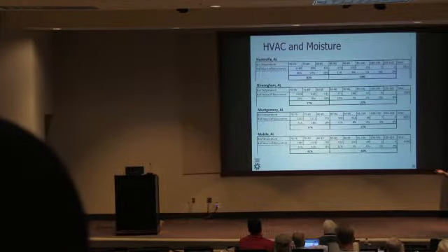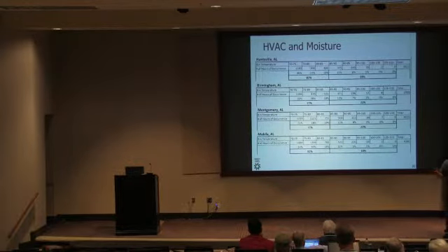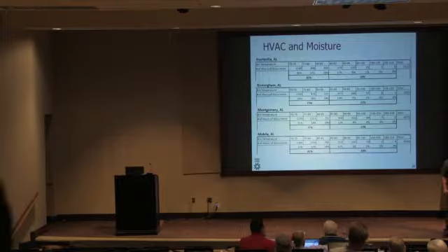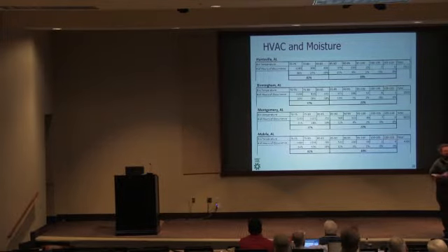You're also going to pay, what? The most upfront cost. But the reality of it is, that is the best possible system, and that's really where our industry is going in the future, variable capacity equipment, so we can oversize to meet any of these ridiculous loads that we're hardly ever going to see, but we can operate efficiently for the loads that you're actually going to see 75 or 80% of the time on the house. And you get better dehumidification in the process.